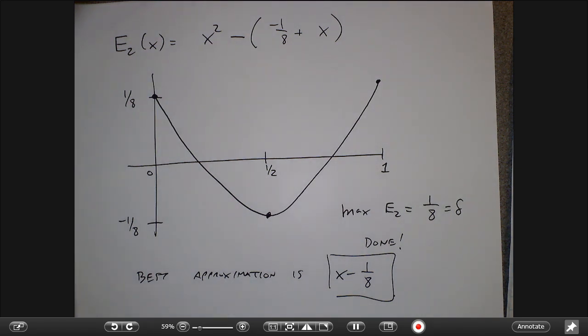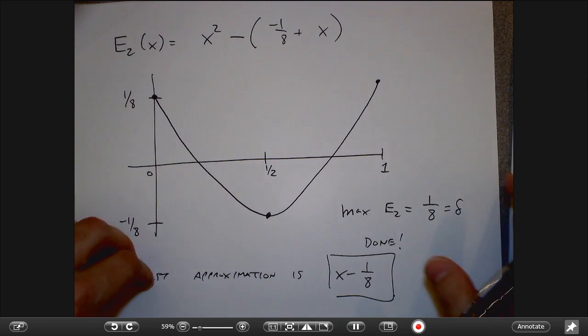So you can always obtain some Equiripple filter. But the thing I haven't talked about is how you force that Equiripple filter to satisfy the constraints in the passband and the stopband that you gave in the very beginning, right? The problem is that it may not be possible to satisfy those constraints given the number of filter taps that you asked for, right?